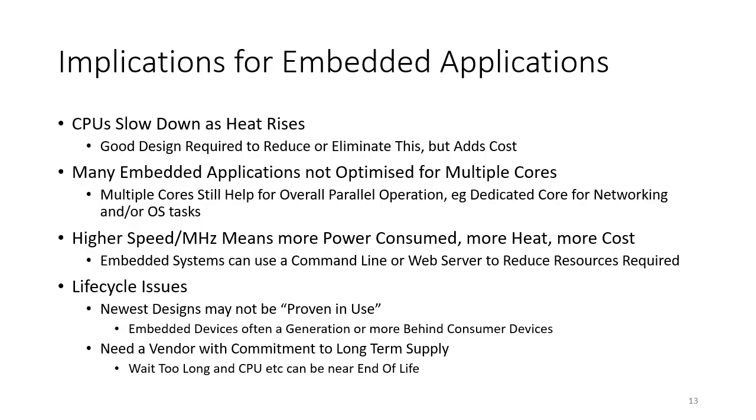If you're in an industrial environment, if the temperature goes up, you don't want to lose control of your application. So you need to make sure your design will run as fast as possible at as high a temperature as possible without any degradation. Again, maybe less important for an HMI SCADA application, but if you're relying on your industrial device for your control, it's very, very important it can run at full speed at maximum temperature.